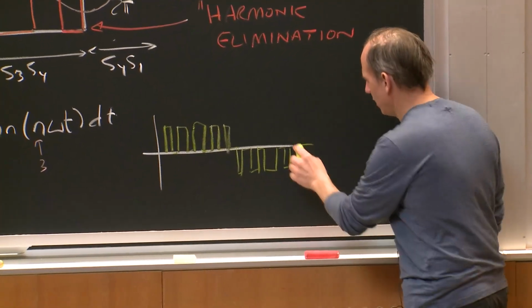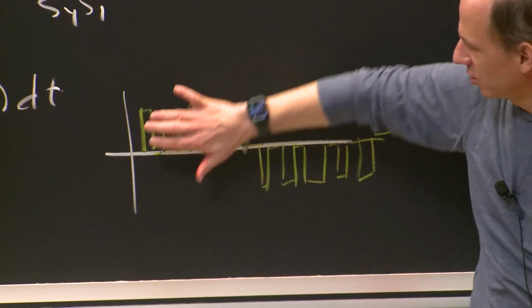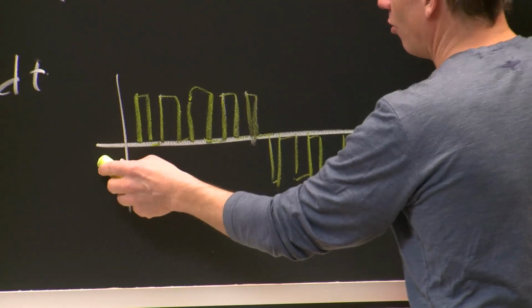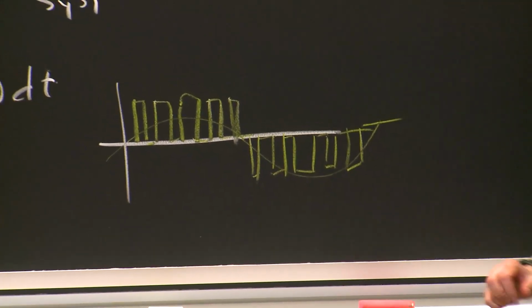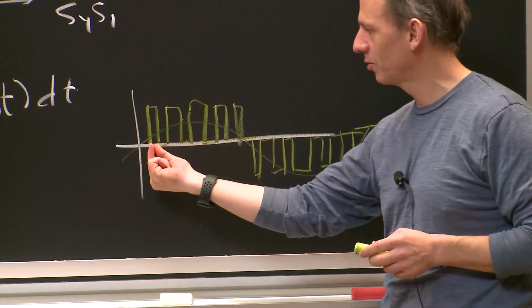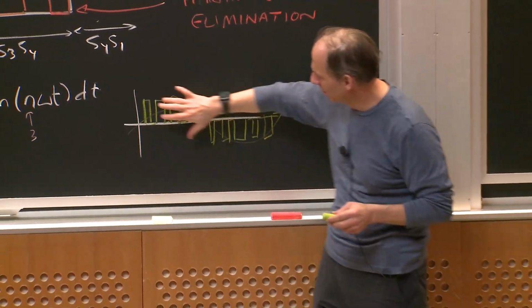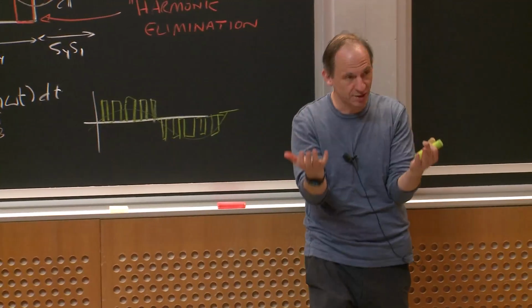Something like that, right? I don't think I have the right number of pulses here, but I have something shaped to generate a set of pulses that make this, at least at low frequencies when I filter it, look closer to a sine wave. Okay, maybe these middle pulses would tend to be bigger than these edge pulses. Okay? And I pick the pulsing times and positions exactly to give me this magic cancellation.